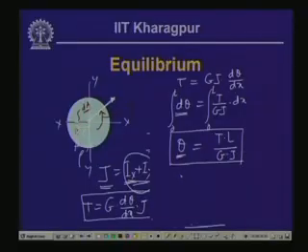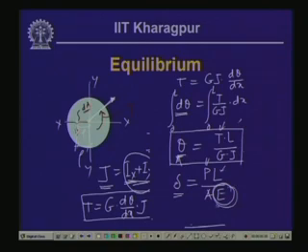Theta is the change in rotation between the two ends over the length L, which is subjected to a twisting moment T. Now, if we compare this expression with the deformation derived in module 2, wherein the bar is subjected to a load P, we said delta is equal to P L by A E. Here, analogous to P we have the twisting moment T, along with the length of the bar; in place of the modulus of elasticity we have the shear modulus, and in place of the cross-sectional area the polar moment of inertia J comes into the picture.